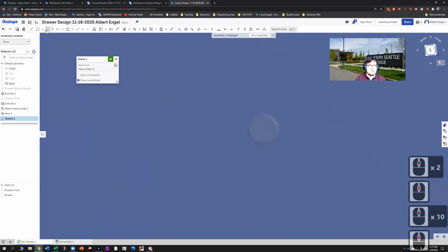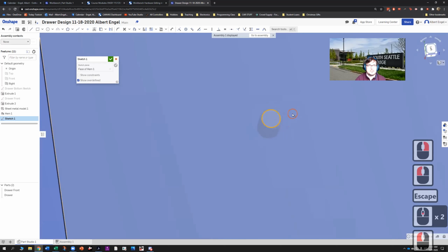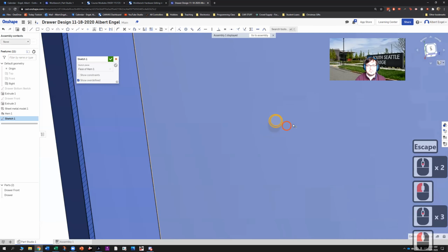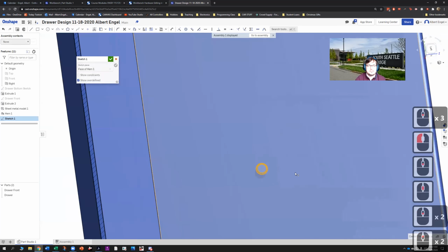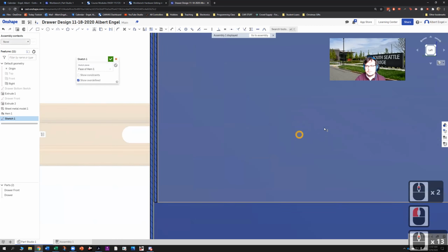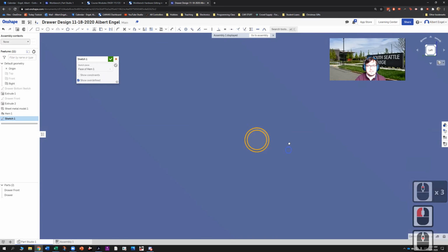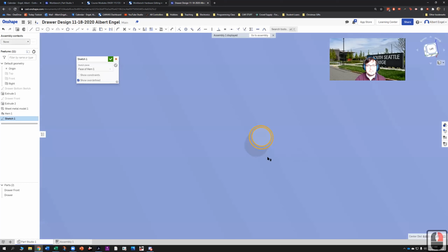holes. So I'm going to come in here and start making some center point circles. I'm going to try to select that shape. Now you'll notice I'm having some trouble here. If I grab this one, I grab this one, I can actually use this to add geometry. But this is the tricky part. I have to do one little tiny step here to make that happen. So I've got this showing up here, but it's not actually showing up in my sketch because it's actually a little bit above my sketch here.